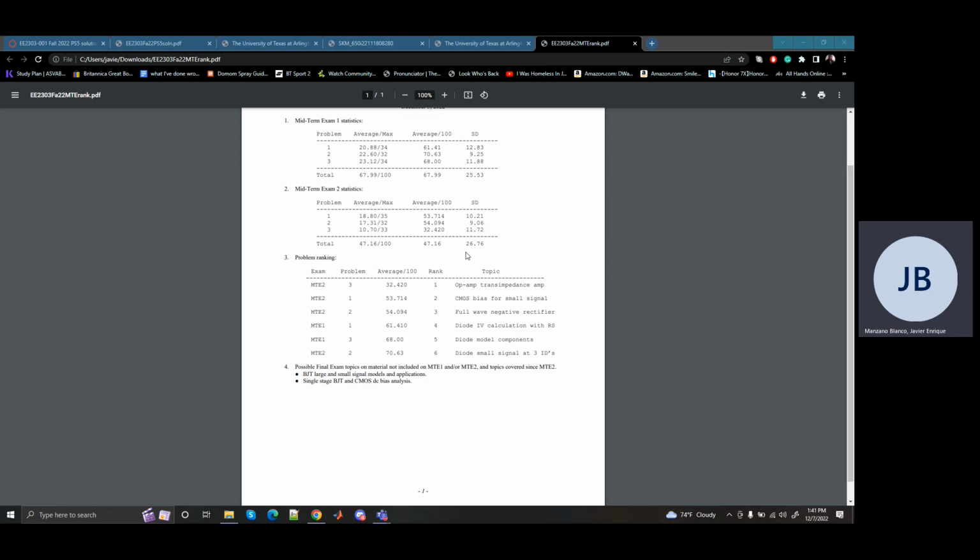So you break it up and you go, this is a section of linear devices that I can turn into a Thevenin's equivalent. This will be a section of linear devices, or you can find the biasing of this, turn it into the small signal, then it'll be a linear device that you can look at.